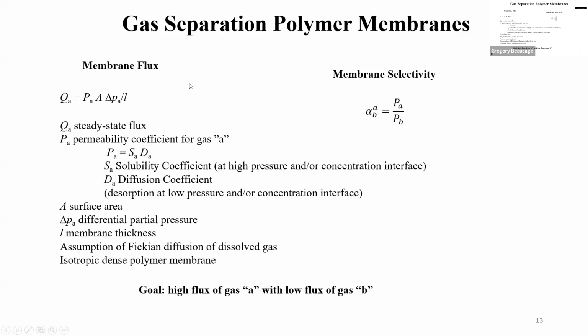So you want to get A out of the thing, like fresh water, and then you want to get rid of the B, so you want to get rid of the salt. If it's gases, it's like pressure A or concentration A, concentration B. So there's a selectivity number. You want that to be a huge number, in other words 100 or 1,000. For an industrial membrane, you want it to be above 50. Then the flux has to be big to get what you want out of it.